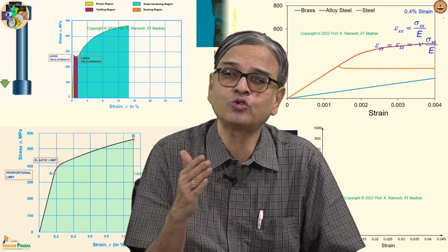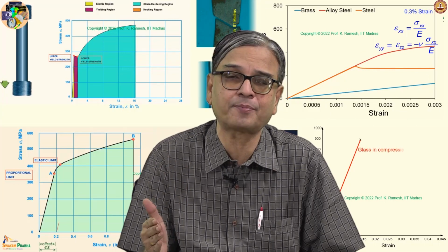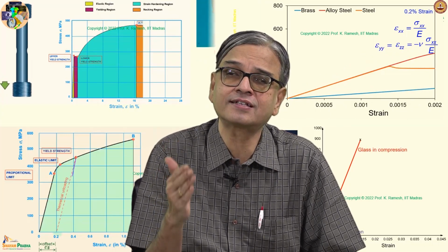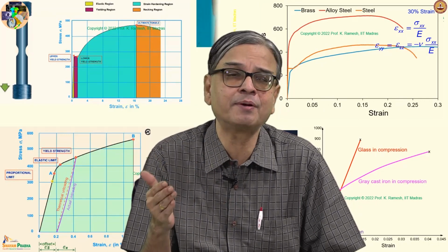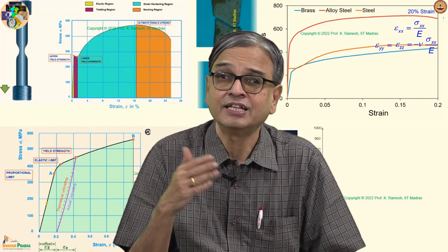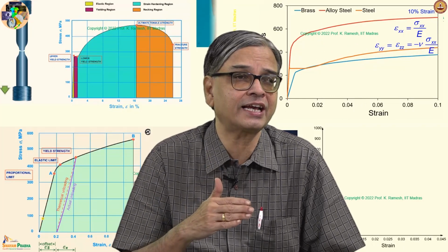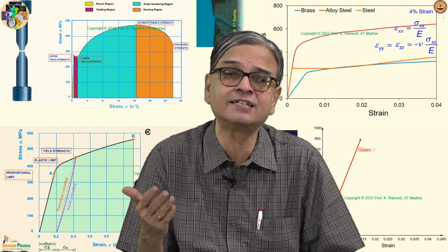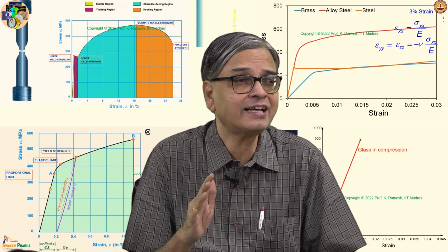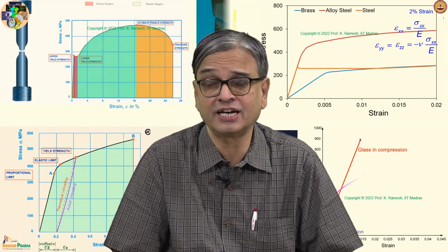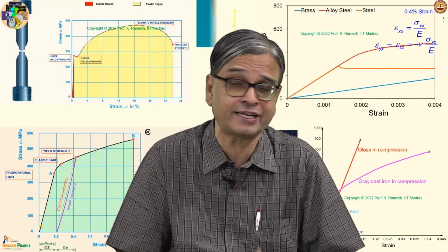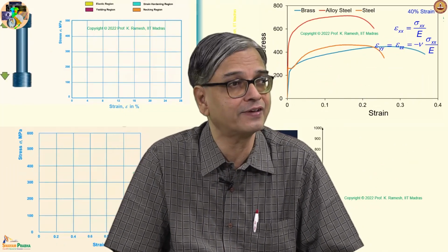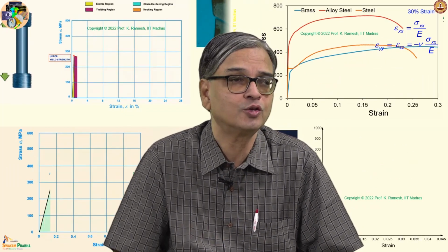When we go to state of strain at a point, we have also discussed about the directions of maximum axial strain. These principal directions and principal planes are identical for an isotropic material. That is not the case when you go to an orthotropic material or an anisotropic material. It can in principle be different depending on which way you load the system.